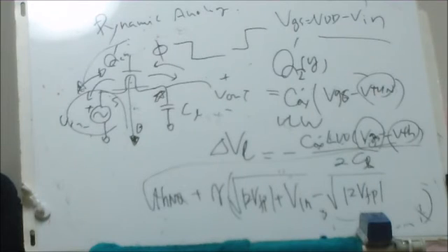This illustrates the problem associated with charge injection. The change in voltage across C load is non-linear with respect to Vin due to the threshold voltage. Thus, it can be said that if the charge injection is signal-dependent, harmonic distortion results. In sample data systems, charge injection results in non-linearity errors. In the case where the charge injection is signal independent, a simple offset applies, which is much easier to manage than harmonic distortion. This will be discussed in more detail in chapters 28 and 29, but it should be obvious here that charge injection effects should be minimized as much as possible.